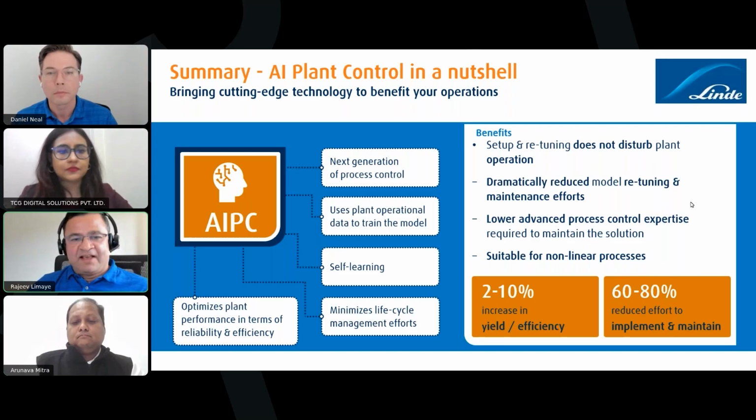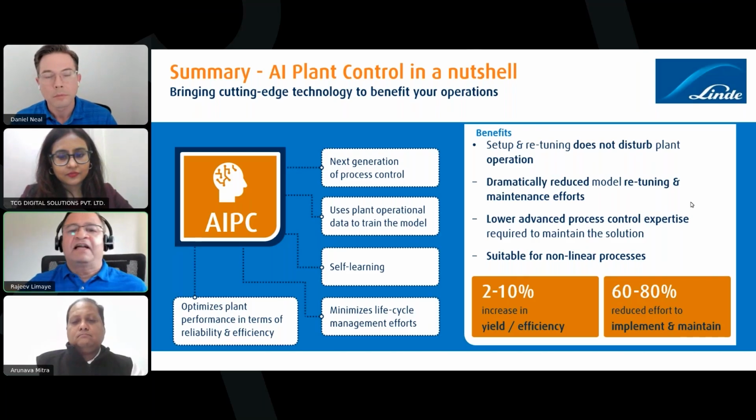Okay. If I understand, your question is whether, in the same unit, it can handle this. For example, if it's an ethylene cracker, there is a cracker, there are separation sections. So typically there's a concept of subcontrollers, we call it the submodel, and each unit will have a submodel, and one controller can handle multiple models, and they can also handle some interactions. So that's how we handle it. But if they are completely different plants, then a separate AIPC instance is installed at each plant.